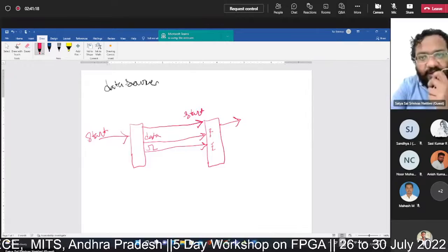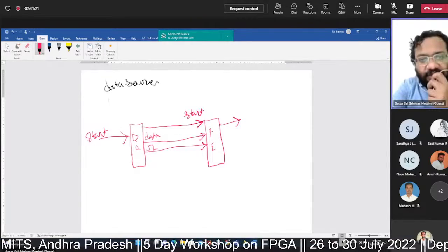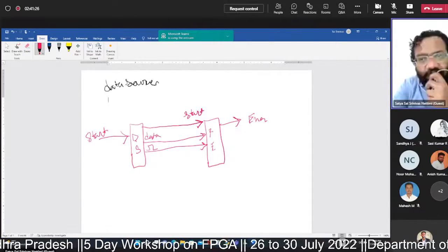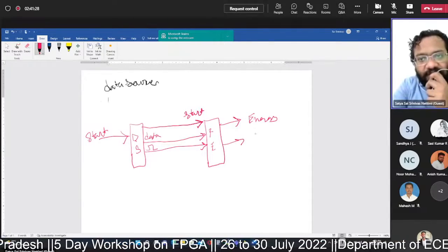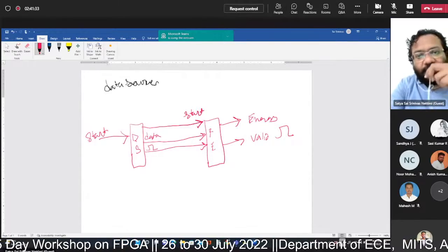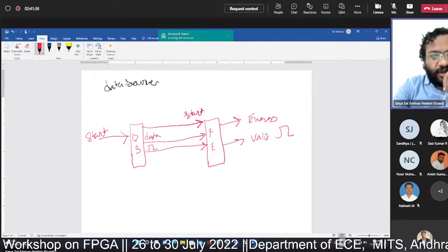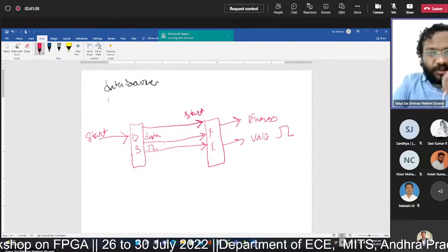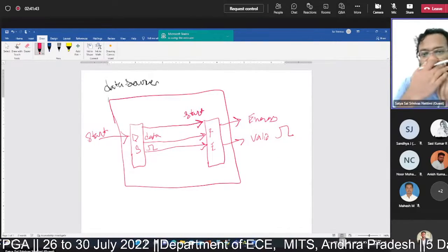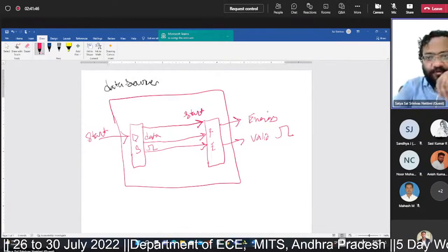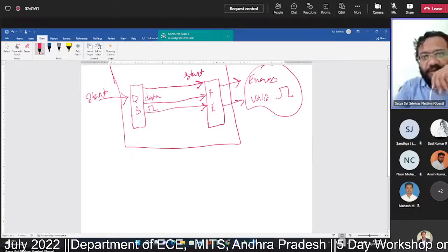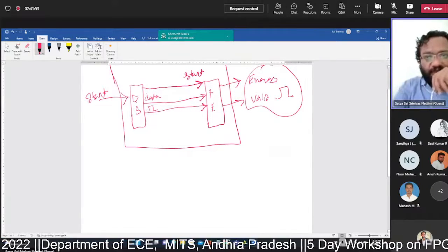And then the frame energy takes the data from the data source, calculates the frame energy, and gives you the energy value. And whenever this energy value is valid, a valid signal will be given. So in this mechanism, we have to do it if you want to implement on an FPGA. This entire block I am drawing should go on an FPGA. Then only you can visualize how the energy is being computed in real time on the FPGA for a signal having finite length samples.